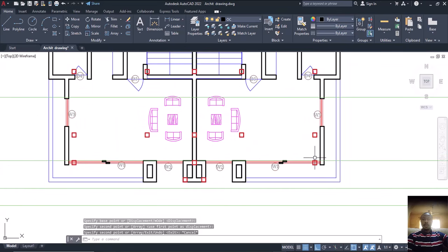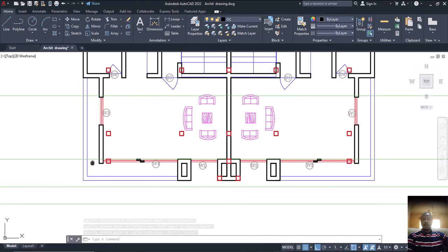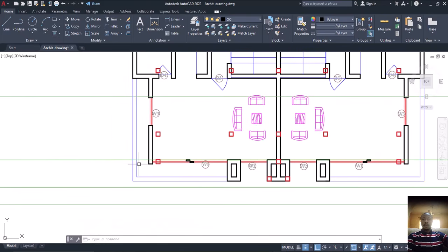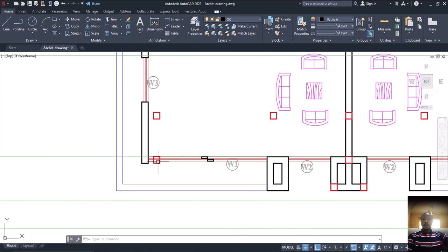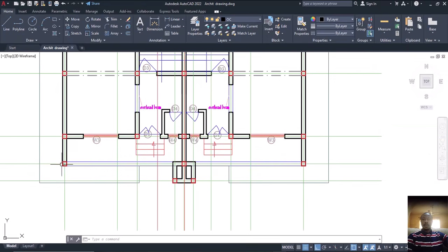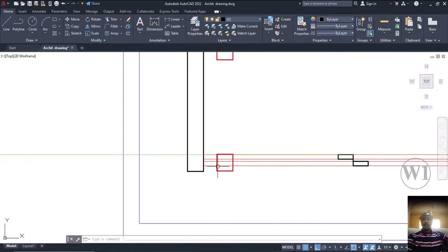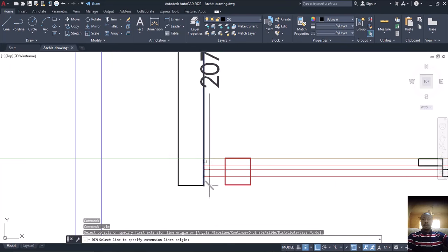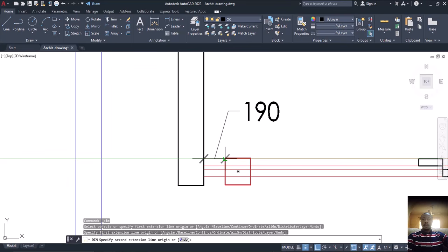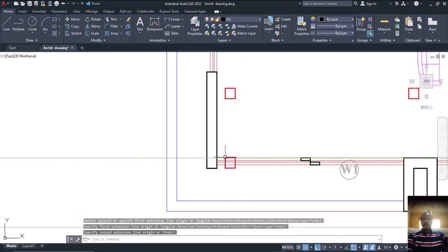So for me, what we are going to do, because there are times you have to liaise with the architect or you take your judgment because looking at the structure. Now for me, shifting this column from this point to this point, automatically in this place it's already outside the building, isn't it? So since the space between here and here is not much, let's check the distance. Can you see, just 190? It's not up to 200. So the edge to edge.